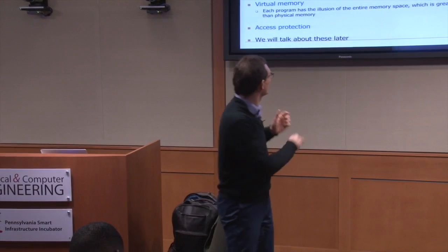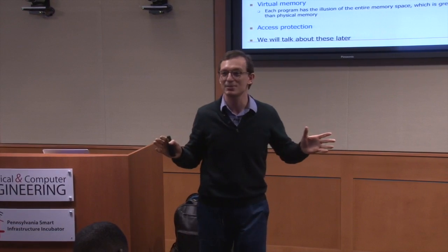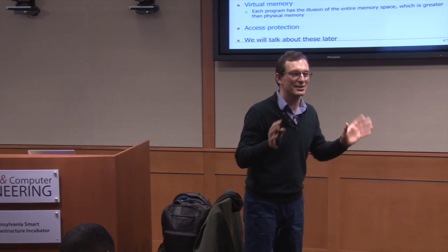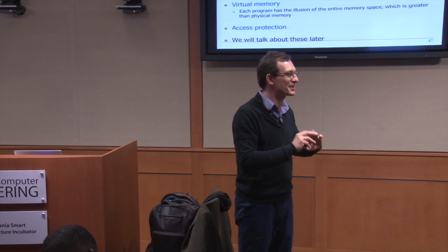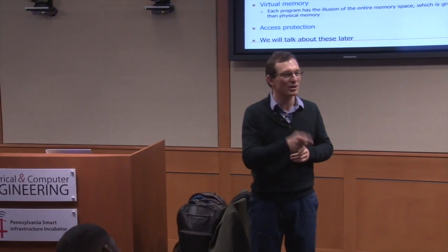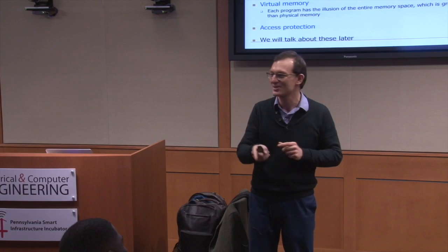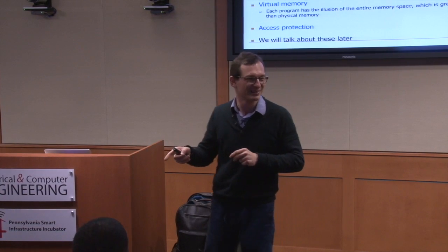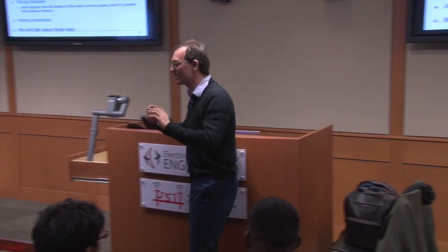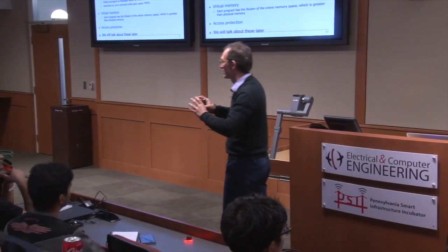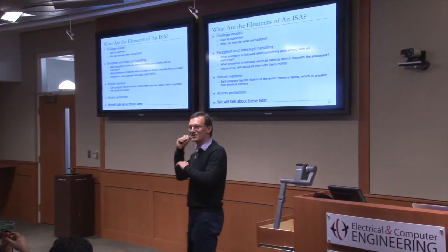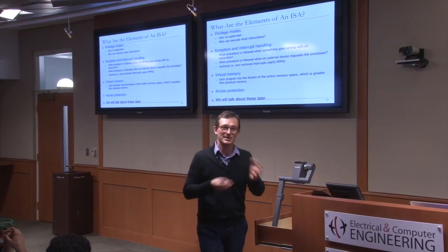Well, the trade-off here: early MIPS, for example, because they wanted things to be simple, said, we don't want vectored interrupts. We want to be simple, so whenever an interrupt happens, the processor needs to somehow figure out who's interrupting. So the processor went through all of its I/O devices and said, did you interrupt me? Did you interrupt me? Well, bad idea, right? In a sense. It may be a good idea as long as you cannot store which device is interrupting you. But now MIPS actually has vectored interrupts. So that's a trade-off also.